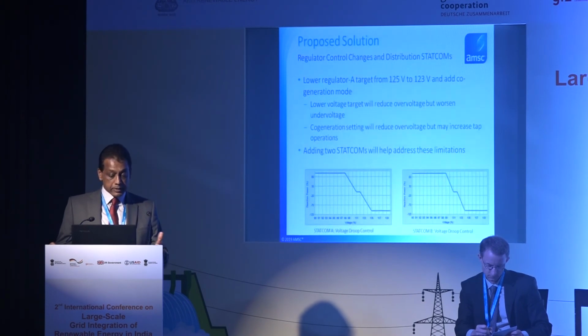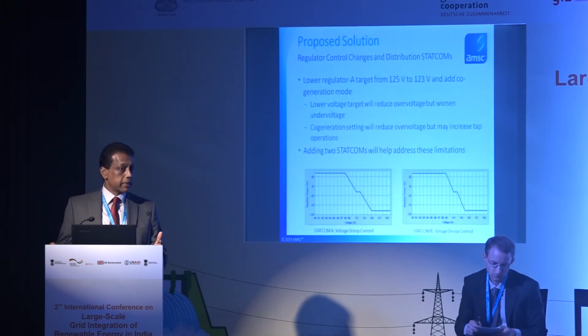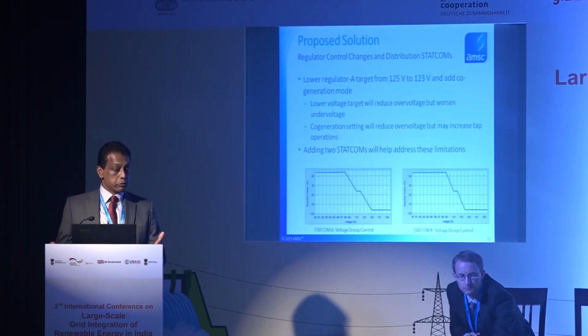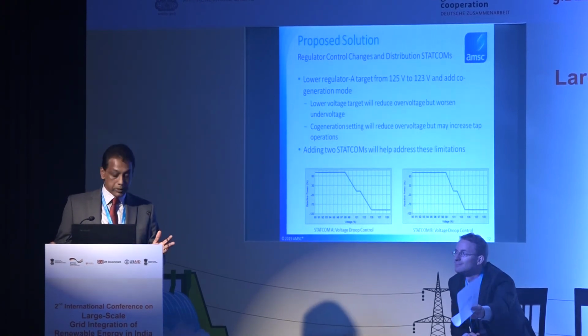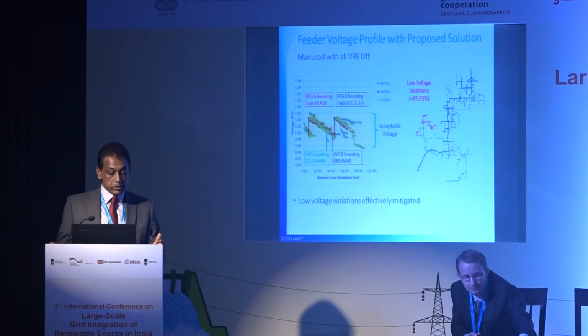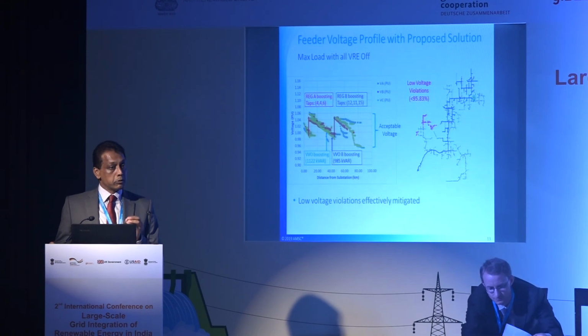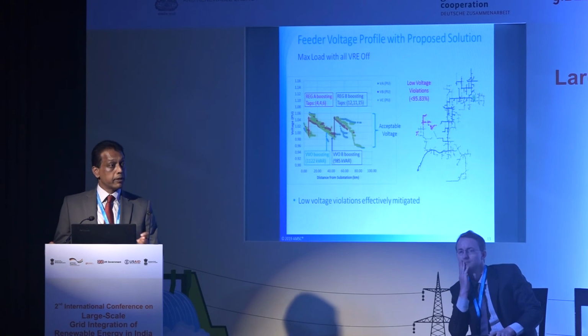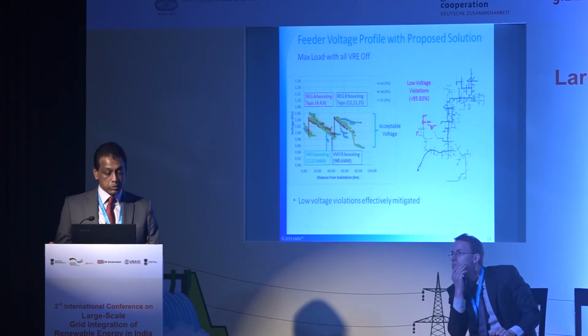So what we've done is provide a STATCOM, which works like a traditional machine on a droop control basis with a voltage set point, and it helps to keep the voltage on that feeder within an acceptable band, whether it's 5%, 3%, or 2%, however you want. You choose the ideal location, do some analysis, and we can help you identify how to choose the best locations.